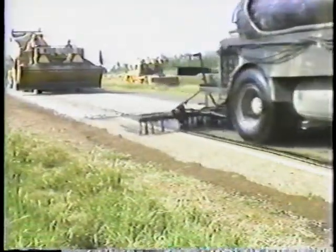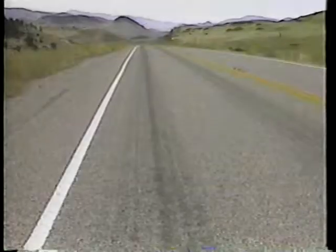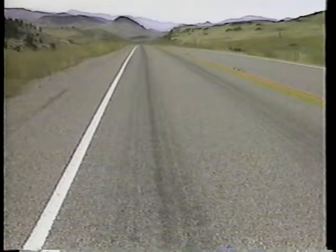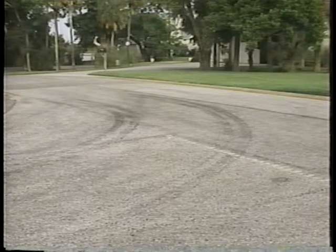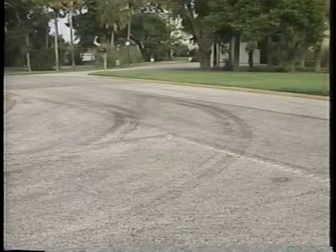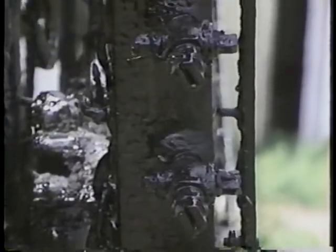Uneven coverage shows up as streaks on the surface. Too much oil in some places, not enough in others. The chips will strip from lean or thin areas, while the oil will bleed in fat or heavy areas. Bleeding creates slippery spots on the surface, a safety hazard. To get uniform coverage, first check the spray bar nozzles. They must be unclogged and uniformly angled, usually 15 to 30 degrees in relation to the spray bar.